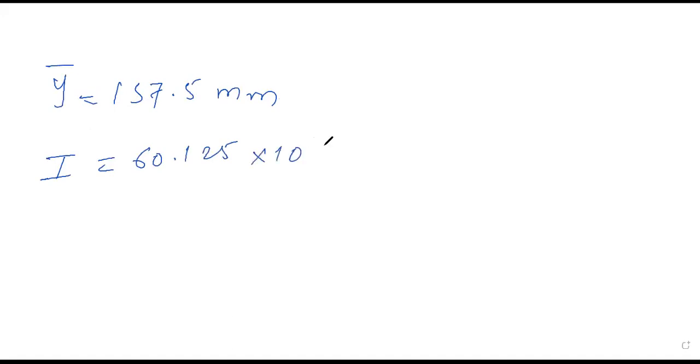For yesterday's numerical, answer for moment of inertia, or before that, y bar is equal to 157.5 mm. Please write down the answer. Please try to solve yesterday's homework numerical. The moment of inertia I will be 60.125 into 10 raised to 6 mm fourth.